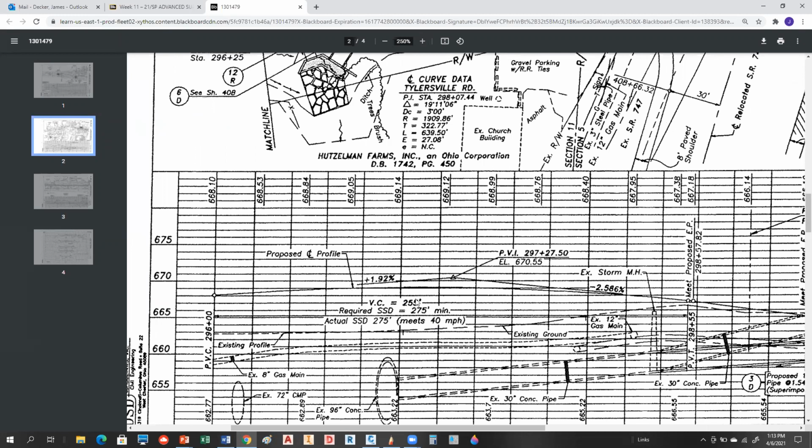And you'll notice it's got a line that comes up. It's got this junction where it meets. That's called a PVI. It's got a station. Then it's got this line going out. And they relate these guys into what we call percent grades. And then down here, you have this thing called VC that stands for vertical curve. And what we're going to do is show you how those guys work. Okay, so that's what we're going to talk about. So let me grab my PowerPoint stuff here.